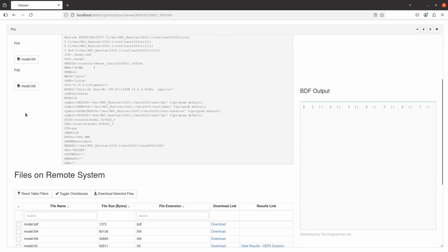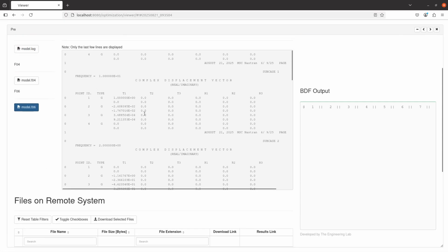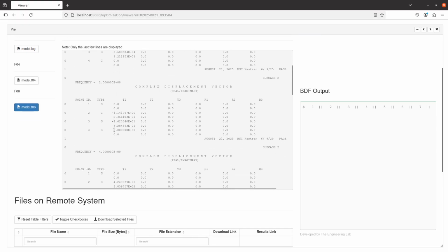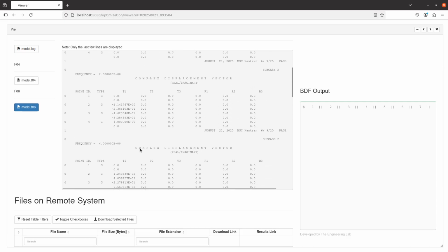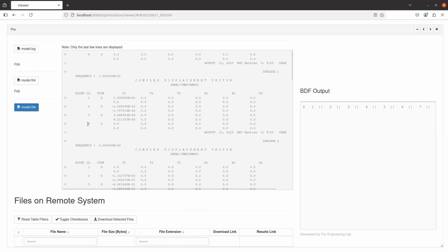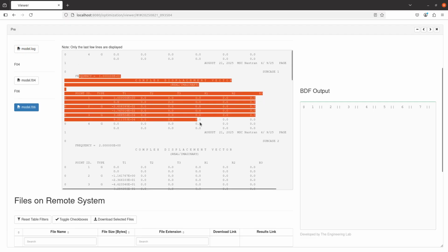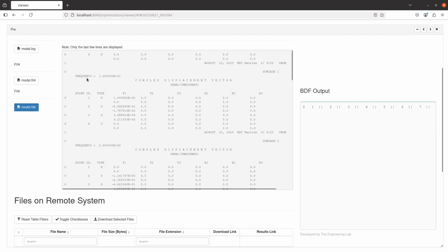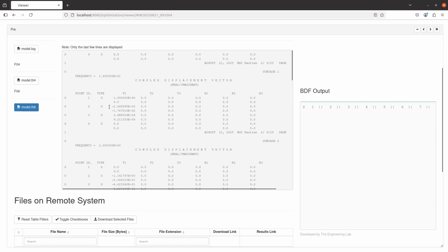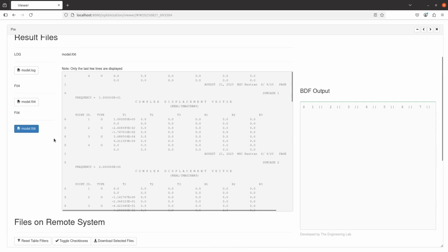Normally what you would be looking at is the F06 file. So here are some examples of what those results look like. I believe we want to look at this for... Oh, I don't like this output right now. Right. So you notice that the format of the output right now is not in a format I personally like. Right now it's outputting all the results for forcing frequency 10. And then here goes row. These are the results for node 1, node 2, node 3, 4, and 5. I don't like this format, so let's go ahead and change that format a little.